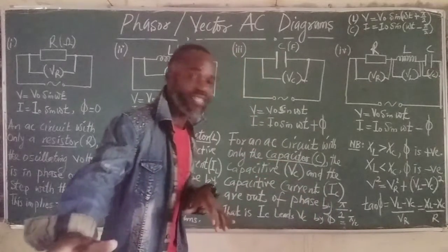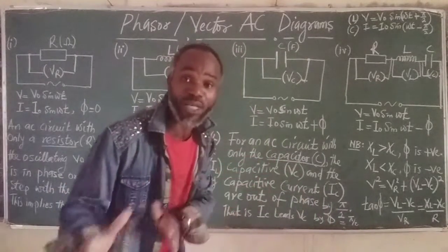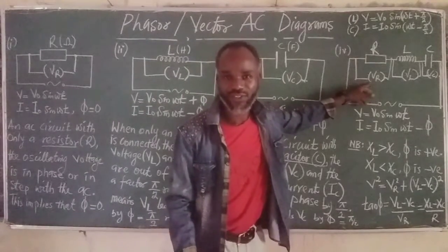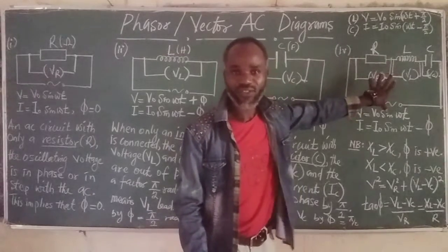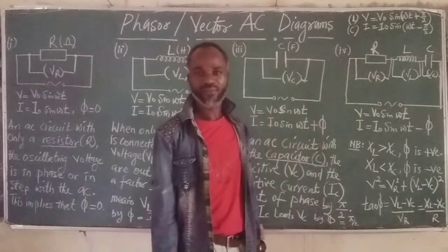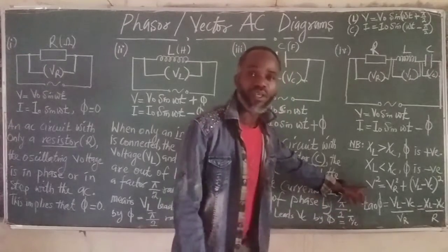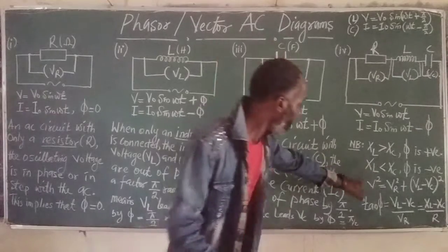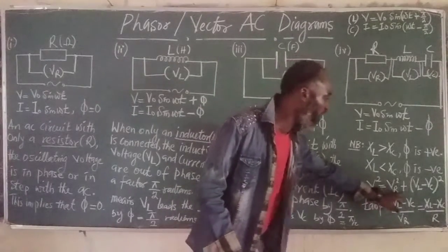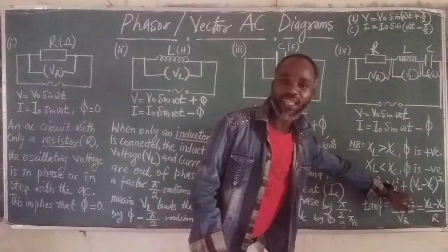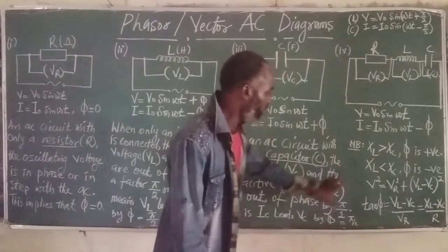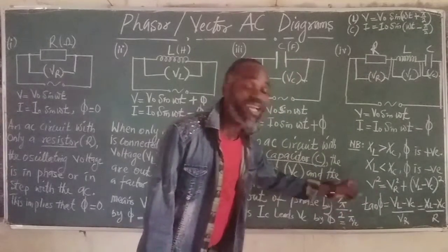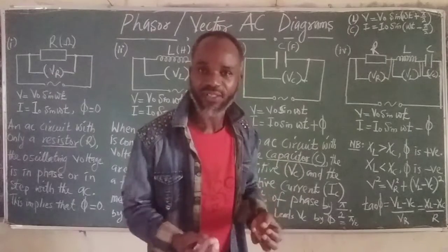And if we understand that properly, we can now calculate the resultant voltage of the entire components in the AC circuit. To do that, we have this. A Pythagoras theorem method can be applied here. And that is V squared is equal to VR squared plus (VL minus VC) all squared. If we take simplification of this, we will arrive at a concrete answer.